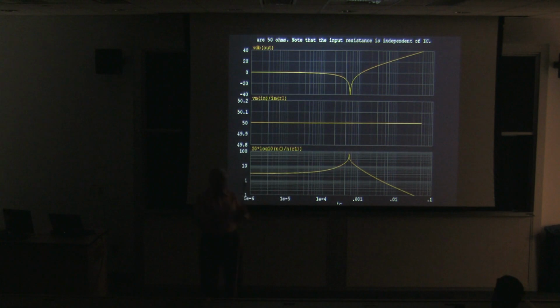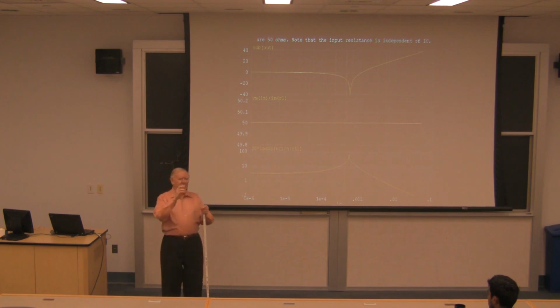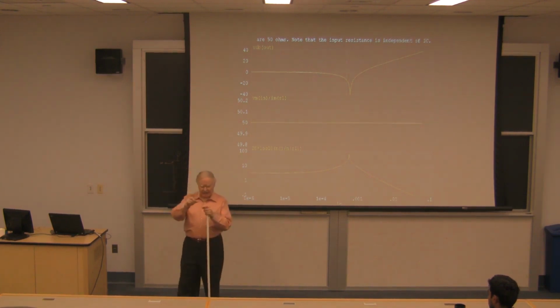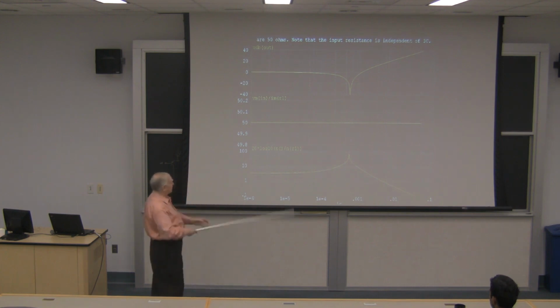Now, that happens because, let me see if I can illuminate that a bit. Ooh. Blinded by the light. I think you can see that if you just visualize that, close your eyes if you like, and visualize that little amplifier, at the input, you have a certain voltage swing, and when the gain is exactly -1, the value of the voltage across the resistor exactly cancels the input voltage, because they're out of phase. So there's a certain magic curve, not very useful magic, where the gain goes to 0 because the voltage across the feedback resistor and the input resistance cancel. And that's that point there.